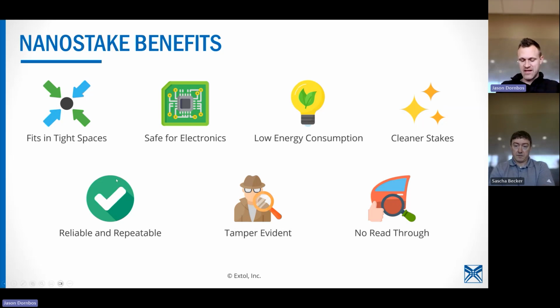What are the parameters I should validate for IR riveting? That's a pretty open-ended question. I guess if you're trying to make sure you have a strong part, I think periodic tensile testing would be appropriate just to make sure that you're getting the strength that you need. But typically what we see with a machine that has staking is some way to monitor that and make sure that the stake was fully formed. So both InfraStake and nanoSTAKE have built-in quality control.